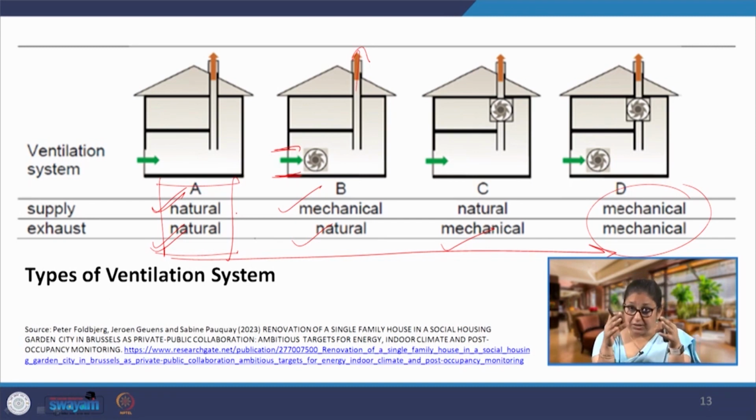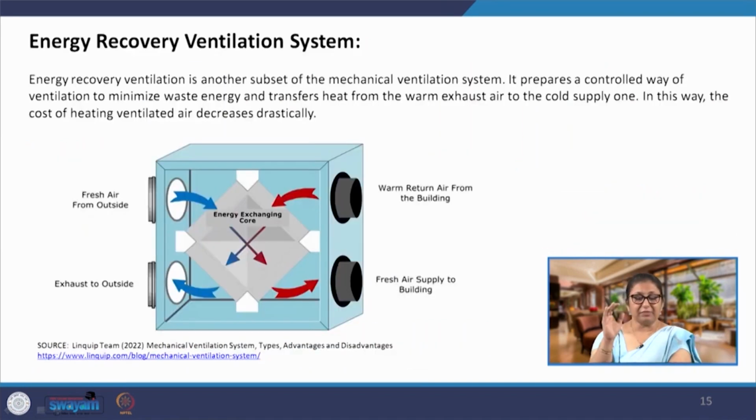So, particularly in case of India, we are a tropical country and predominantly a warm country, a large geographic area of our country, and for a large time of the year it remains comfortable, and we can open the windows. So, there we have to try to have mixed mode, where we have HVAC, we also have mechanical ventilation, but we also have the possibility for natural ventilation. Now, when we are talking about ventilation systems, we can also have advanced measures such as energy recovery.